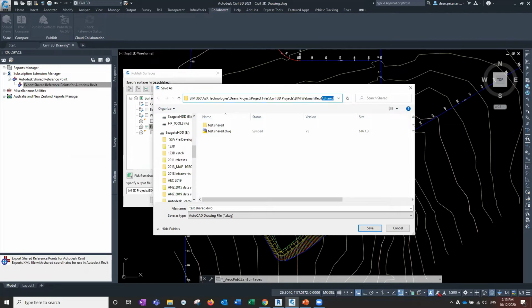And this all runs through this thing down the bottom here called the Autodesk Desktop Connector. So if you're going to use this process, you will need that. It tracks the syncing of BIM 360 and these shared folders on my machine. Let's see, so we're in there. Let's make a new one, let's test shared.